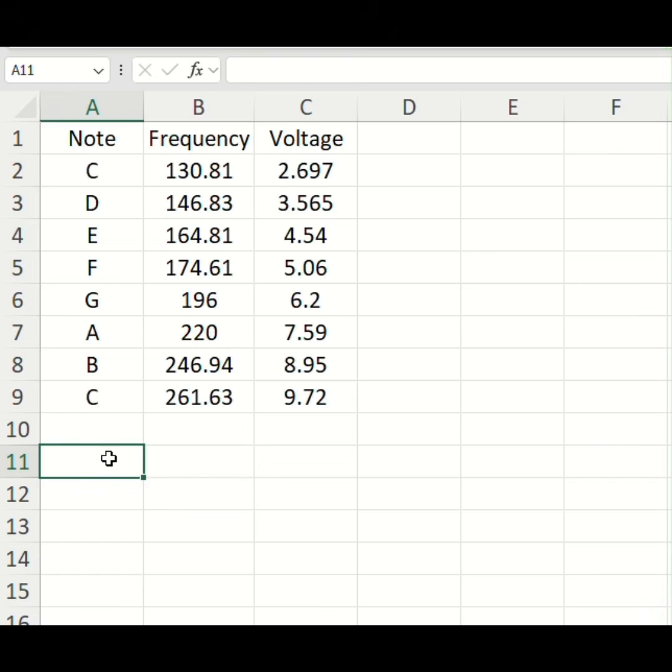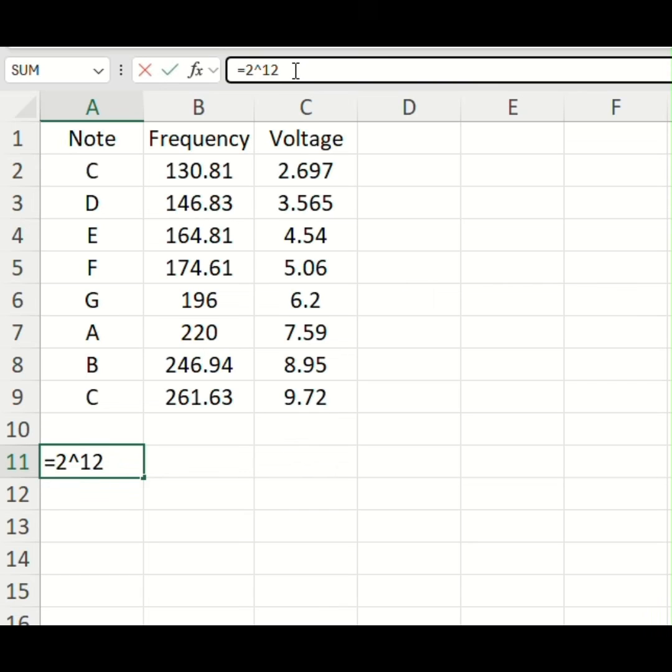Okay, so the next step is we're going to want to convert this voltage into a digital number that we're going to put into that module. So first, let's figure out how many counts we have. This is a 12-bit module. So to figure out the number of counts, that's equal to 2 to the power of 12, except we're going to have to subtract 1 from that because we want to leave the headroom for the 0. We're using a whole number system here.